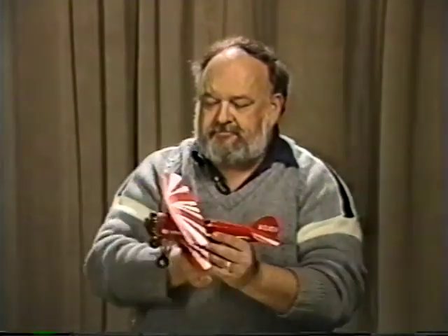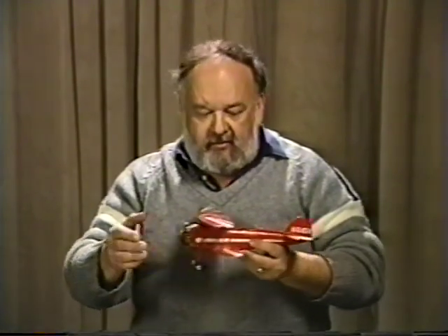The trickier one is the one in pitch. You have a CG travel that you have to worry about. You have several other things. Your wing itself generally is an unstable wing. You have a little camber to it, or when you put your flaps down, it very definitely is unstable. So you use a tail to give you your stability. Look in the books, look at the numbers, take a good idea there.